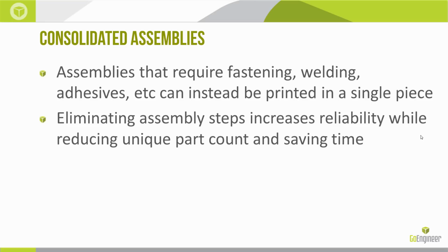That's going to increase the reliability of the part in terms of strength and dimensionally. It's going to be more reliable. But it also reduces the unique part count, it reduces the overhead and inventory needed for that part, and it saves time moving from vendor to vendor doing assembly steps and whatnot. So just a couple examples here.